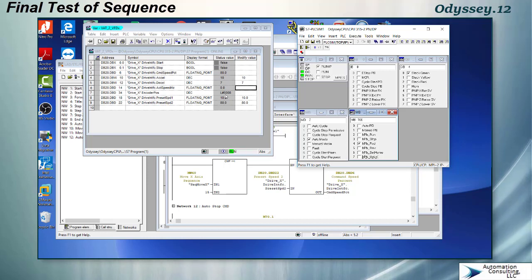And you can see here before, we were stopping at like 5,280, 5,230, that area, just by changing the decel. But now we're stopping at 5,008, which could be considered to be in the range that we want to stop at. I'd say 10 encoder counts, something like that, plus or minus 10 encoder counts. So this is from issuing the stop command right at 5,000. You can see that we only went 8 ticks beyond it. So that's the way this works.